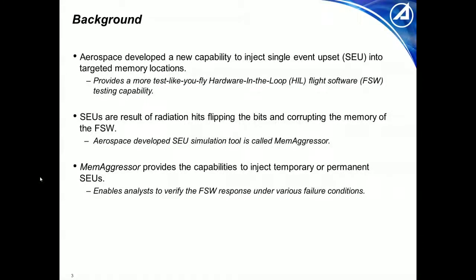So up until this point, we haven't had a good option when injecting single-bit upsets into an end-to-end mission. We have ways to fail sensor feedback from the dynamics into the flight software, but nothing like a single-bit upset.